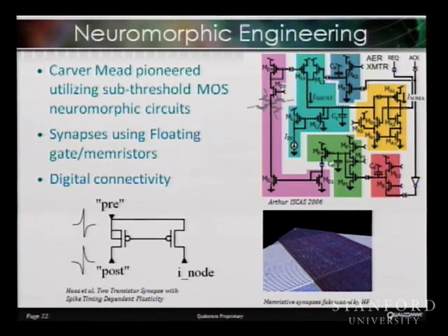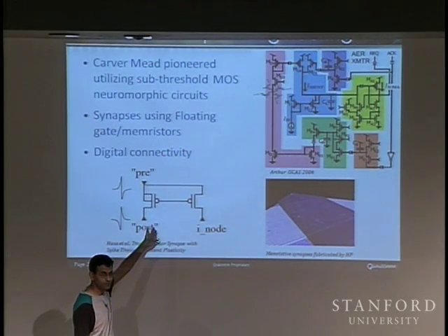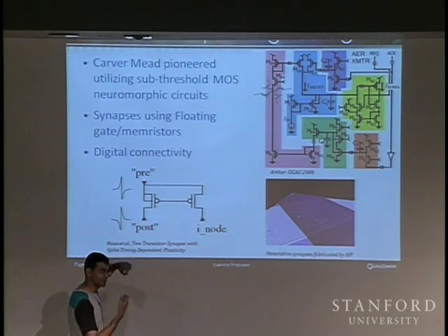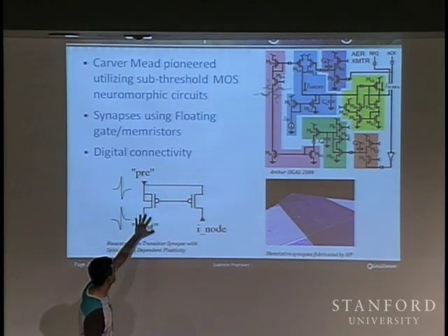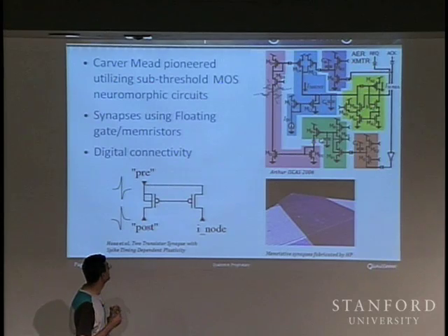Here are just some cool pictures, really, of what's been done. There are people who have built synapses with just 2 transistors. This is capable of learning. It implements STDP, but it does it in an interesting way. The waveforms they apply are analog waveforms, and they're STDP-like, so that the whole response of the circuit is to change its weight based on the inputs. So very clever.